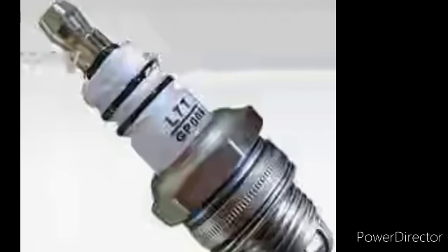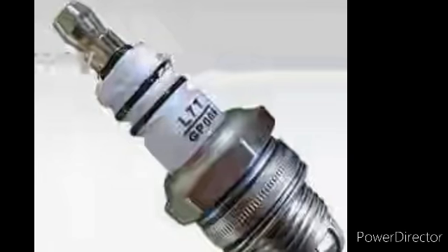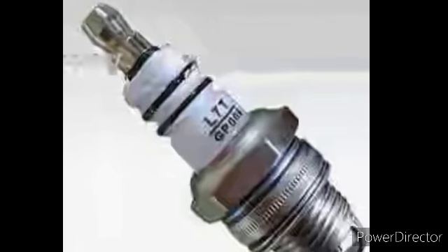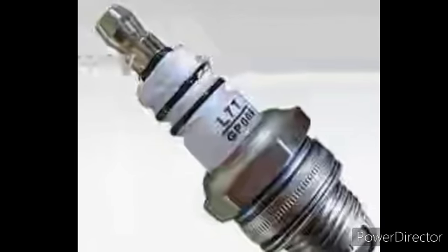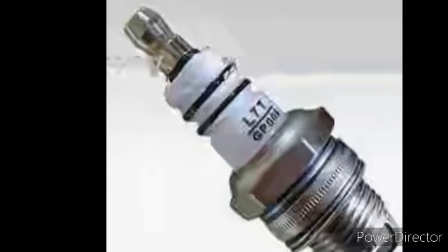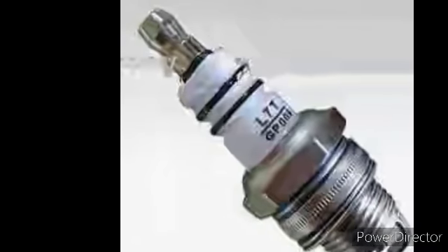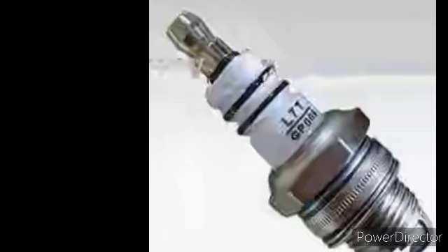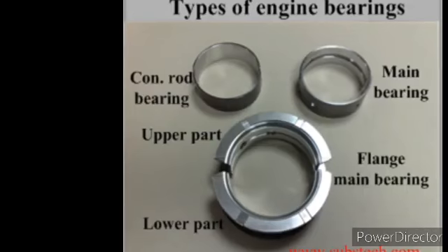Spark plug. The main function of the spark plug is to conduct the high potential from the ignition system into the combustion chamber. It provides the proper gap across which a spark is produced by applying high voltage to ignite the mixture in the combustion chamber.